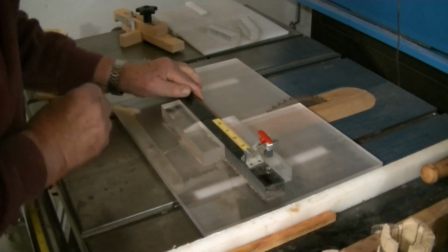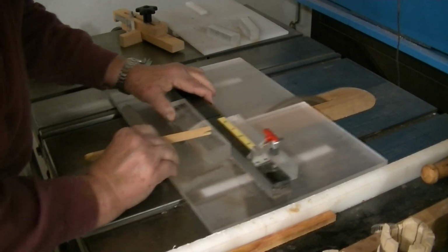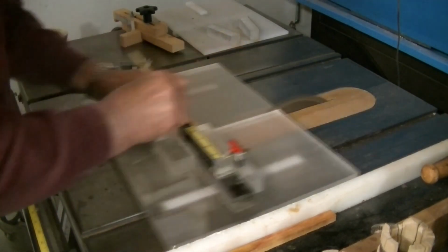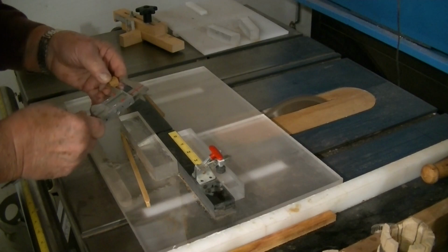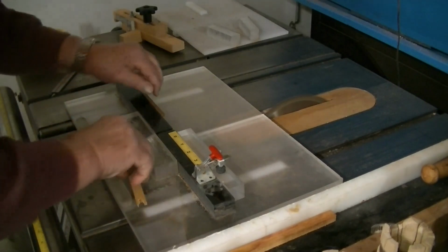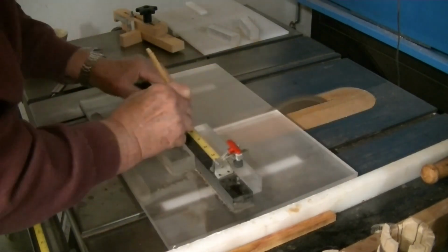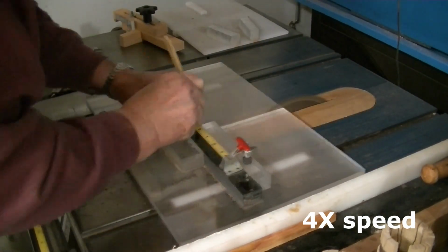So I have the wood I'm going to use. It's a long grain, so I'm cutting across the grain so that the grain alignment will be the same as with the segments. Trim up a little bit to get started. And then I'm going to use a stick simply to hold that piece of wood down on both sides of the blade so it won't go flying out. Just to be sure, we'll check the length. Now that I'm satisfied, I'll go ahead and cut 12 spacers that will be used in conjunction with these segments. Again, fast cutting is a good thing, especially when you can do it with a video.